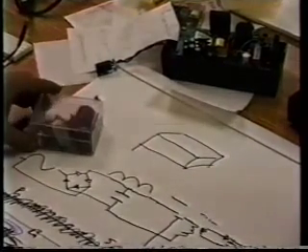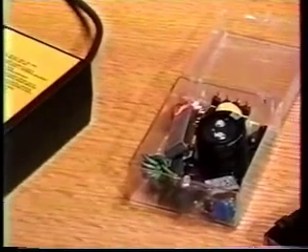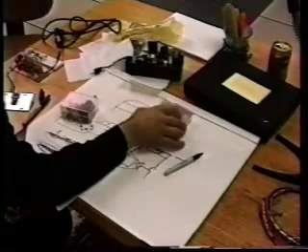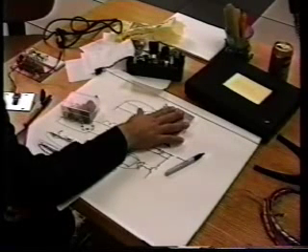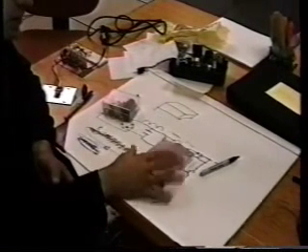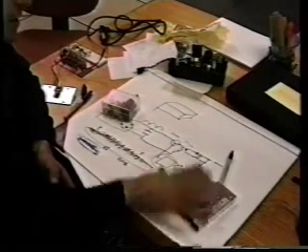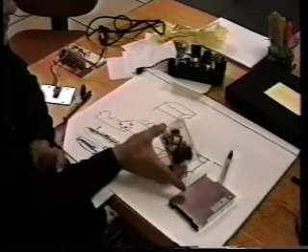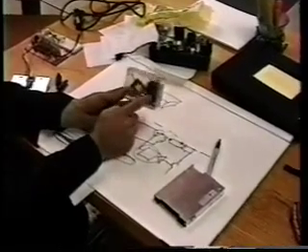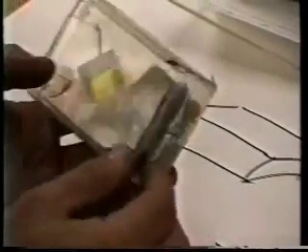In this space inside this notebook, there's space for a floppy disk drive. When it was removed, it'd be nice to put a power supply in there. So we started thinking, how could we fit this thing in there? The first thing to notice is this big capacitor. It's probably a third of the volume of the power supply. We could take the capacitor out. The power supply would only produce power 85% of the AC cycle. This is okay because portable computers have battery backup.